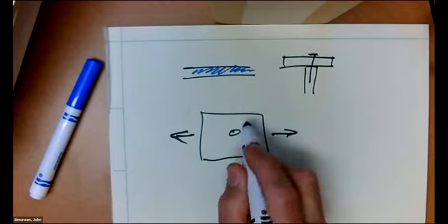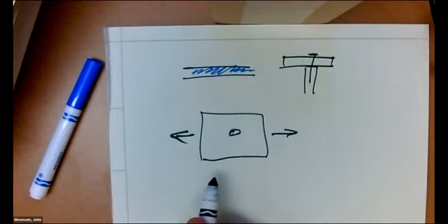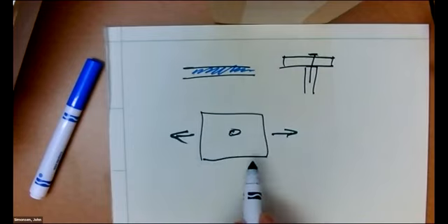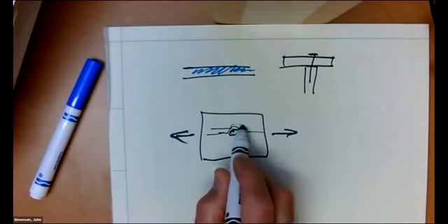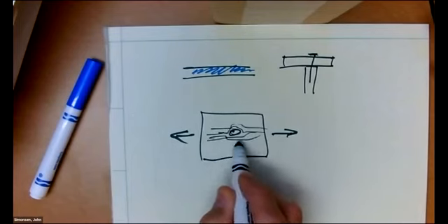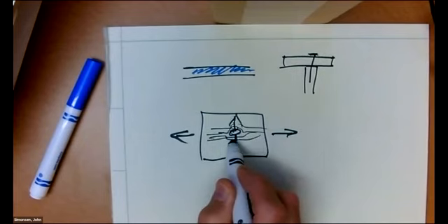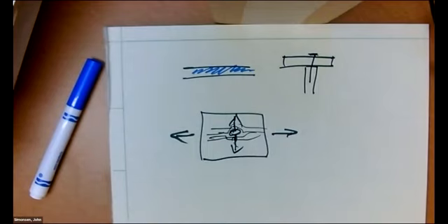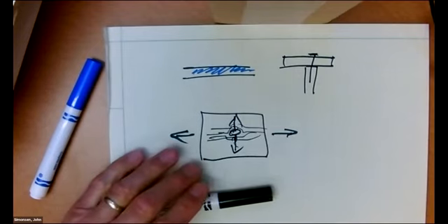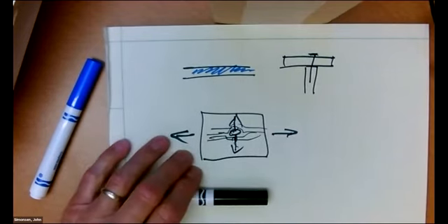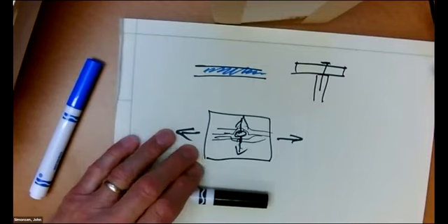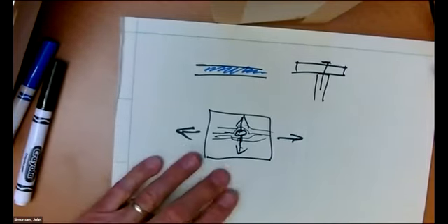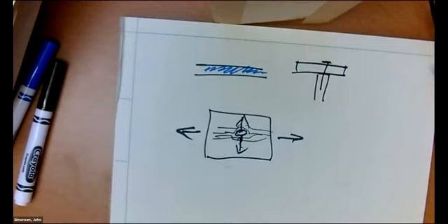Okay. So when you pull this way, when you have a defect and your stress is in this direction, the stress concentrations go like this, right? So your highest stress is actually in this direction, and it'll break in that direction. So if you're using a nail or a screw or a bolt, you're actually putting defects into your substrate, whatever you're putting it into. If you use adhesives, then you can avoid that.